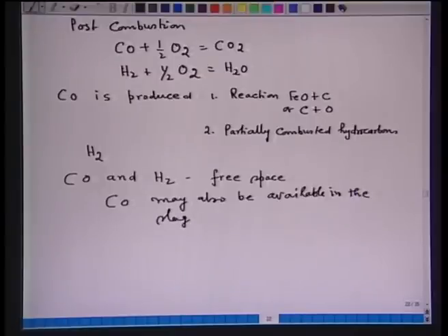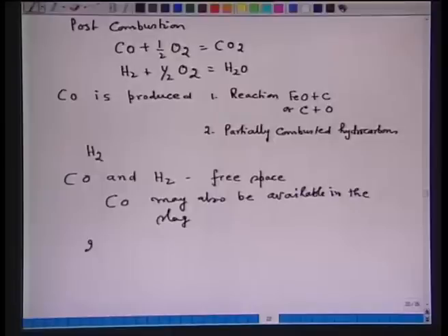So, that means the post combustion of carbon monoxide and hydrogen can occur either at the freeboard or within the slag. Typically 20 to 30% post combustion is attained in the slag, and 80% is attained in the freeboard.